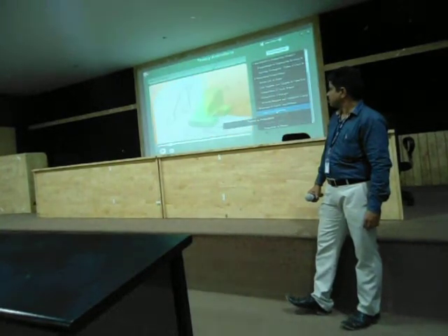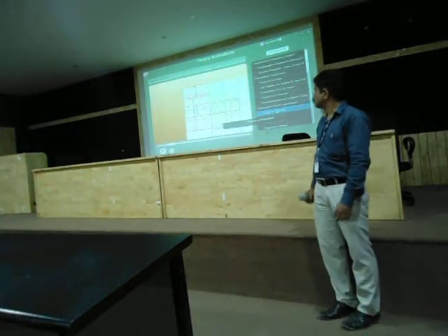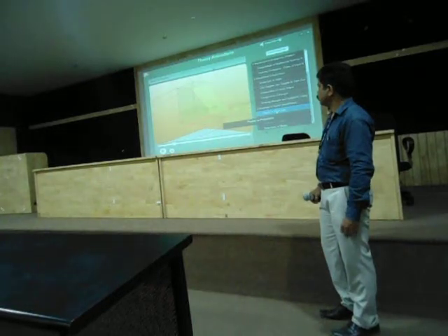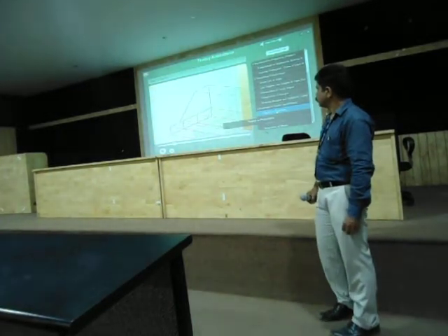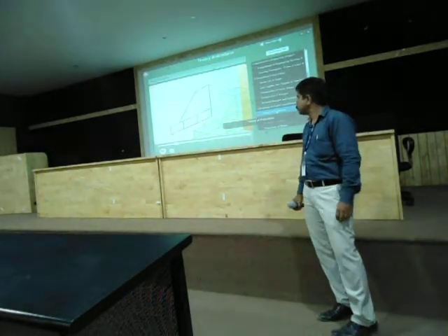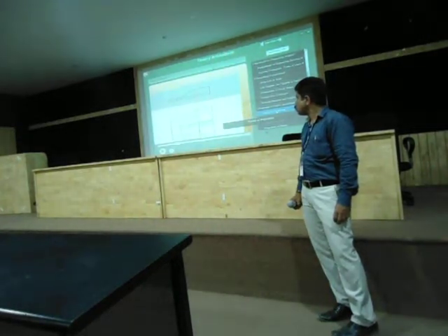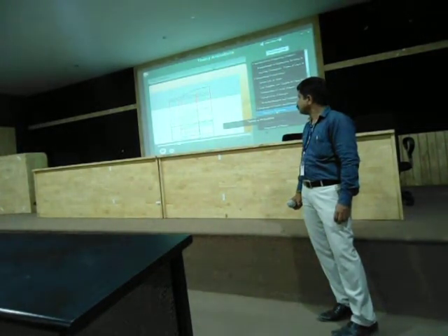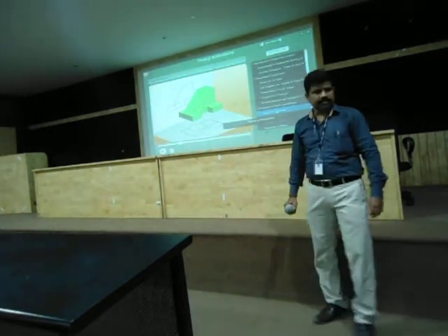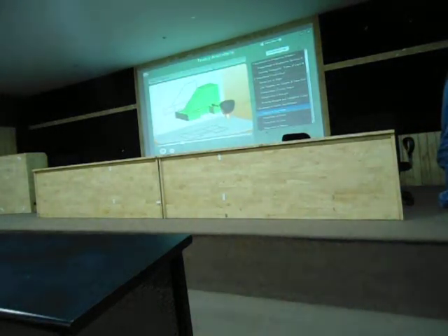We will use orthographic projection where lines of sight are parallel to each other. These lines emerge from the corner points of the object and strike the projection plane. The image formed on the projection plane is known as the projection. The lines of sight are also known as the projectors. The size and the shape of the projection depends on the angle at which the object is being viewed.